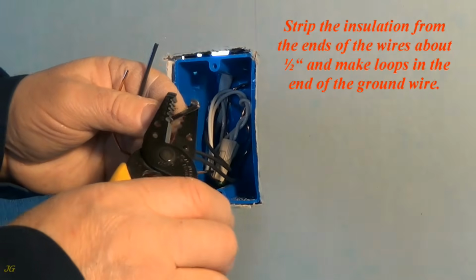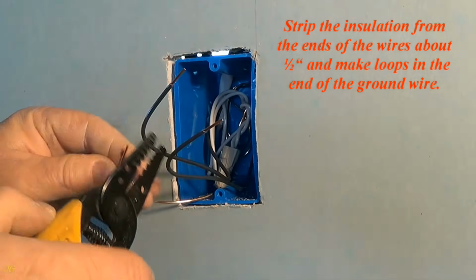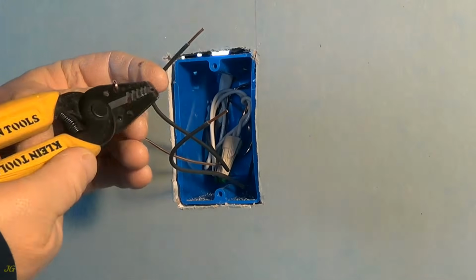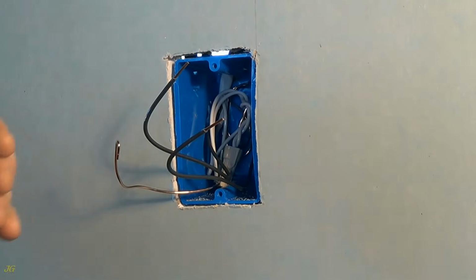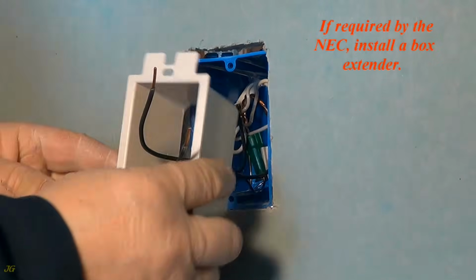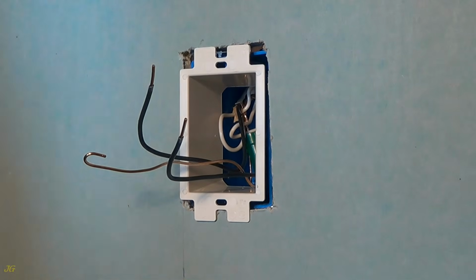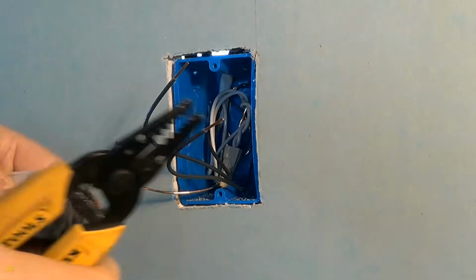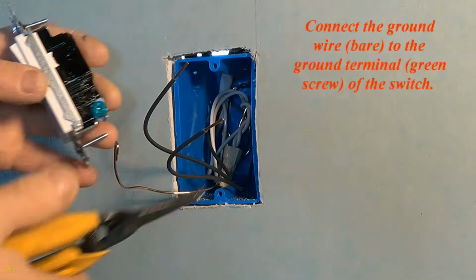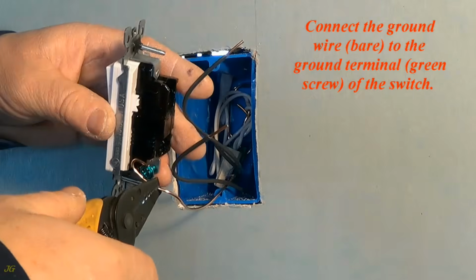Strip the insulation from the ends of the wires about 1/2 inch and make loops in the end of the ground wire. If required by the NEC, install a box extender. Connect the ground wire, bare, to the ground terminal, green screw, of the switch.